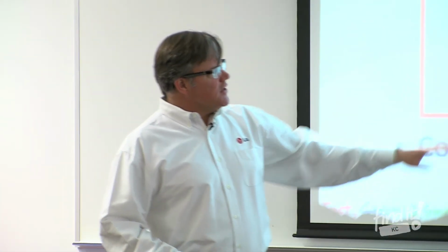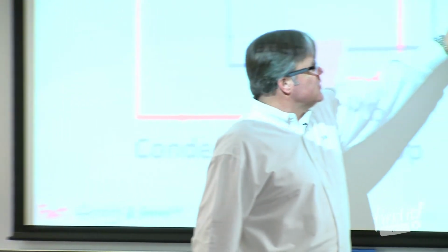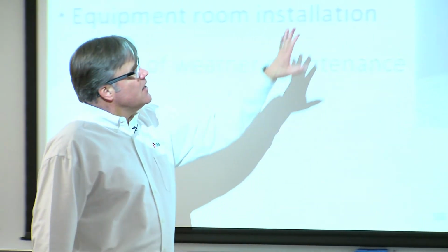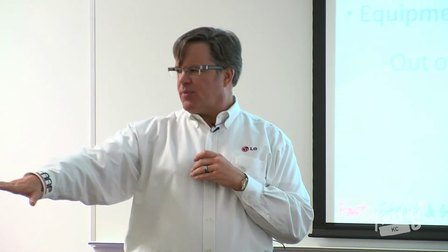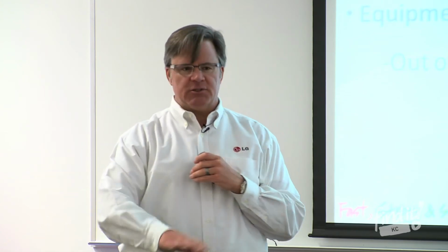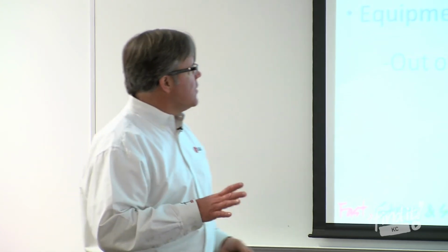The refrigerant management stations here would then be mounted inside. It'd look kind of like this. You'd have a rack of them inside in a small mechanical room, maybe one per floor as you go up through a building, so that water piping just runs that corner of the building to each mechanical room, and then on each floor, you've got refrigerant piping stretching out and serving each space. So water systems is one of the things.